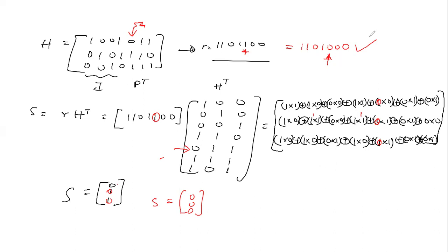code. But now, this brings us to another important metric, which I would love you to take note of, okay? Because if you consider what we have here, that is the syndrome, we have that the syndrome is the same as the received bit sequence times the transpose of the parity check matrix.